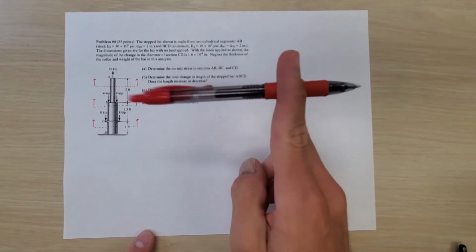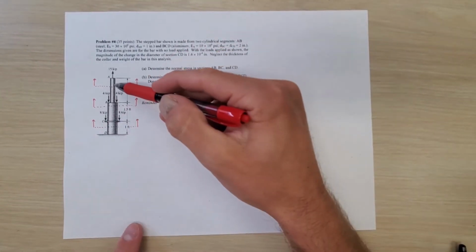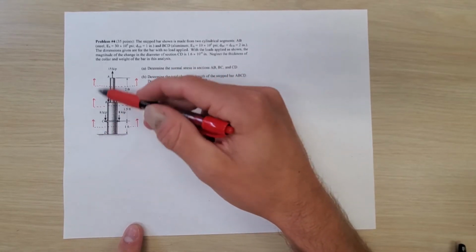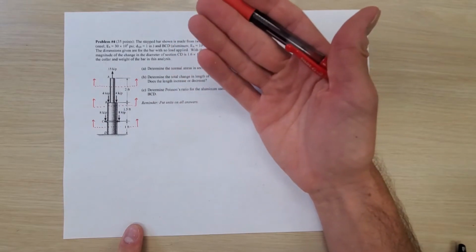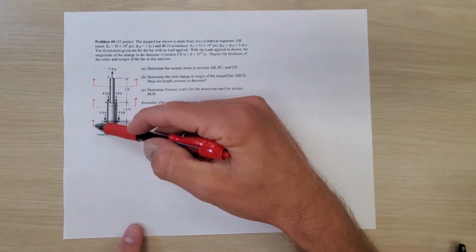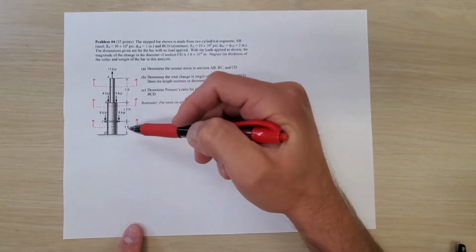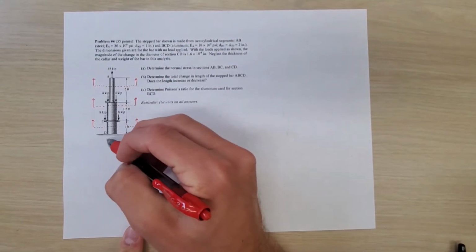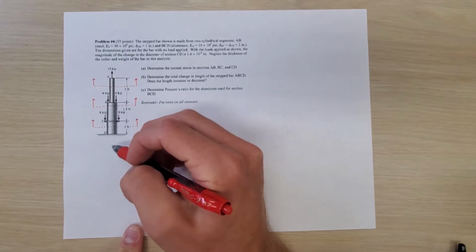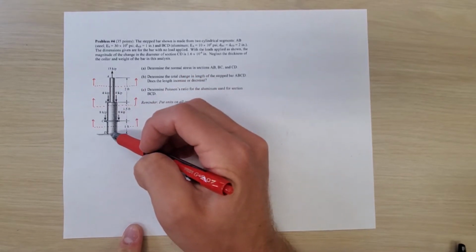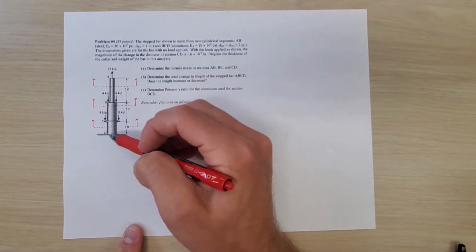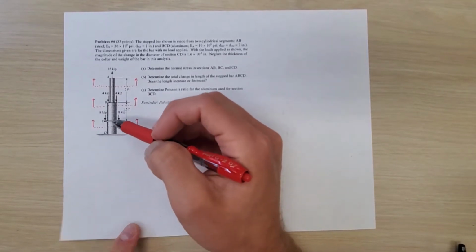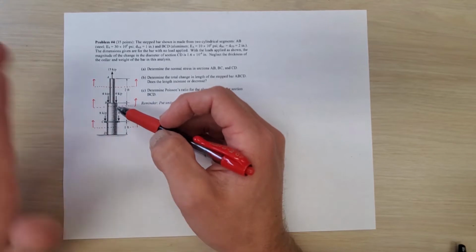So I've got my handy dandy red pen here, and I've drawn a section cut through AB, BC, and CD. I've included arrows that face up because in my problem, I'm going to consider each of these section cuts to be looking up. The reason I do that is so that we don't include the fixed support down here at the bottom. Technically speaking, this would have three reactions. It would have a force in Y, an X force, and it could have a reaction moment. So I don't want to have to solve for any of that stuff.